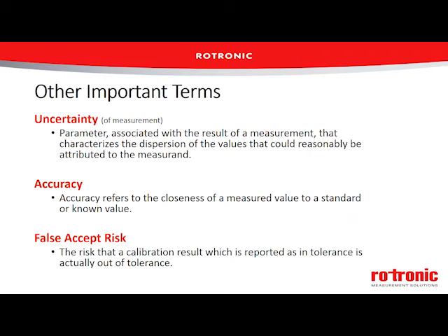This often will get calculated or estimated by a calibration lab and put on the certificate, but then end users often will need to add maybe long-term drift or some other uncertainty components that the laboratory might not know for that specific instrument. So all of these build into the overall uncertainty.